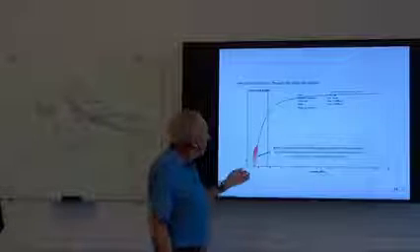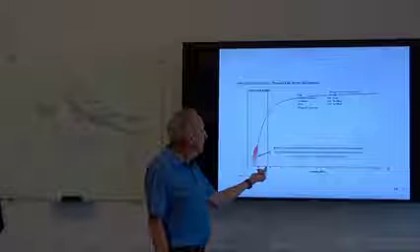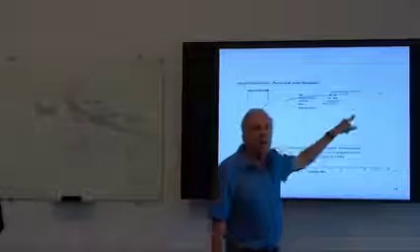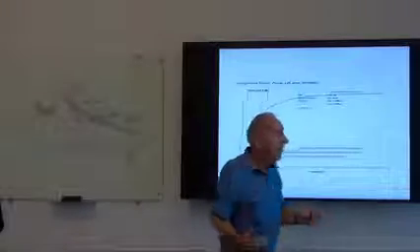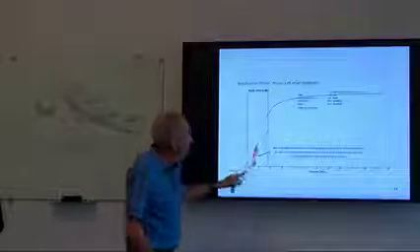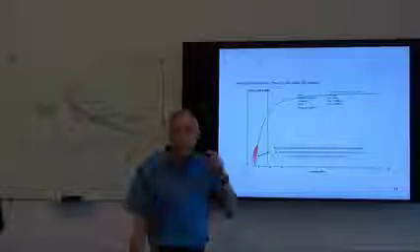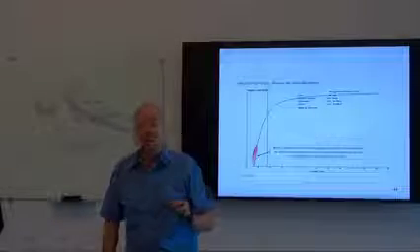We've seen circumstances like this where people have tried to run plungers, and they think, well, when I open my well at surface, I hear a very high gas flow rate. My plunger should be running. And yet, deep down in the well, we have a very low gas velocity. And I'm going to tell you that it is gas that is moving our plunger.